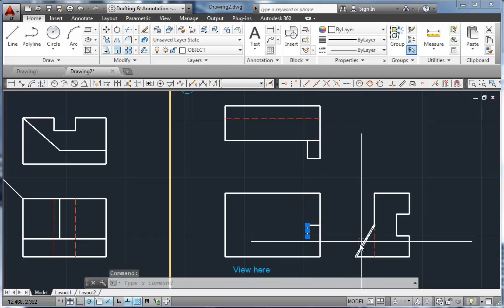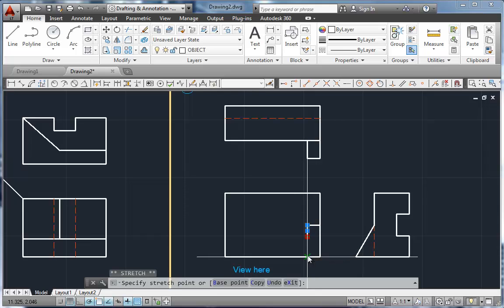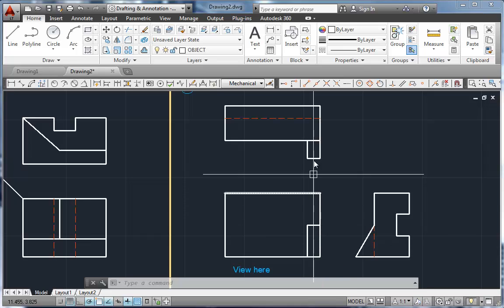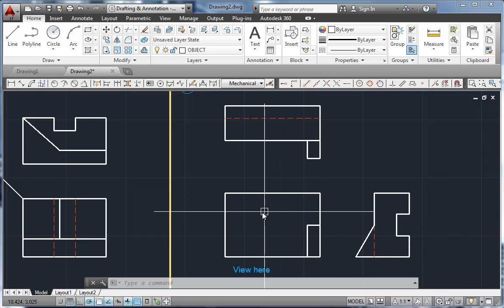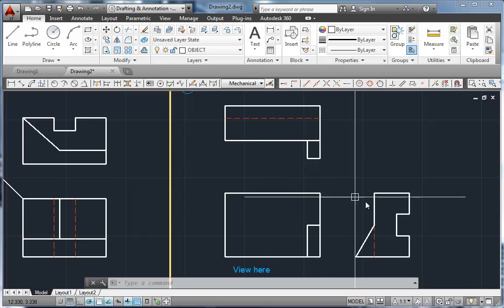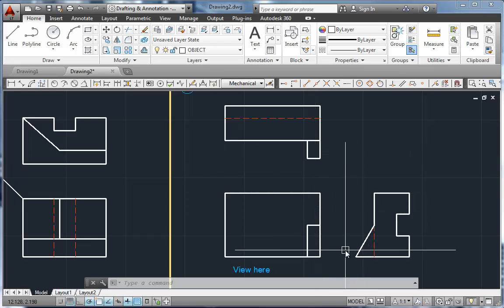And that surface goes all the way to the floor. So I'm going to bring that on down. So that is this little surface. This is an inclined plane right here, not a normal plane. So it shows as a plane in two views, as an edge in one view. So normal surfaces are a surface in one view, an edge in two views. Inclined surfaces, or foreshortened surfaces, tend to be shown as a plane in two views and an edge in a third view.